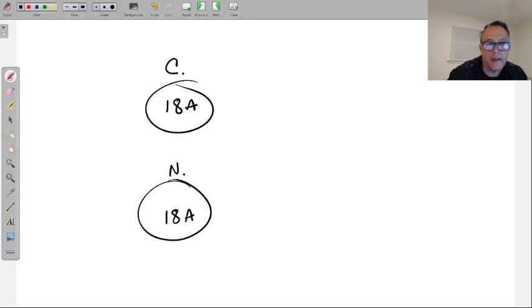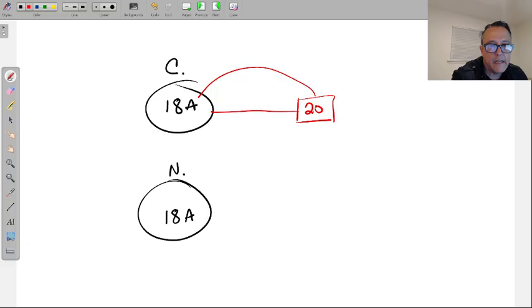Just 18, and it's going to be for a reason. When I go to get a breaker that is going to be energizing this circuit, I can't buy a 20 amp breaker for this. Even though it does seem like I could, because that's 18 amps and this breaker is 20 amps. So it covers the 18.